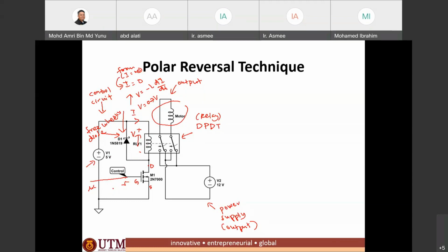When I turn on and then turn off the signal, it sends a false current back to the main control circuit, to the microcontroller, because it is interconnected through the MOSFET. Basically, it sends a signal and resets my microcontroller.